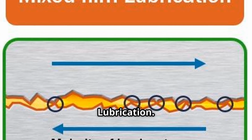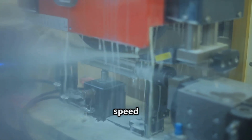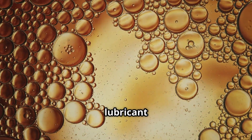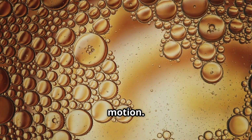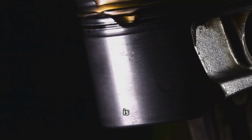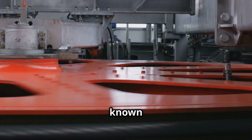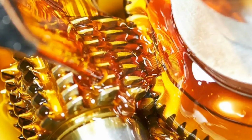Mixed lubrication. Generally speaking, boundary lubrication is dramatically reduced as sliding speed increases, creating a wedge of lubricant film between the surfaces in motion. As the potential for asperity contact is reduced and film thickness is increased, the coefficient of friction drops dramatically to the condition known as mixed lubrication.